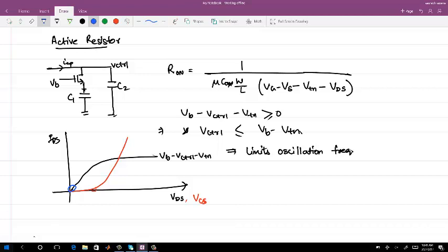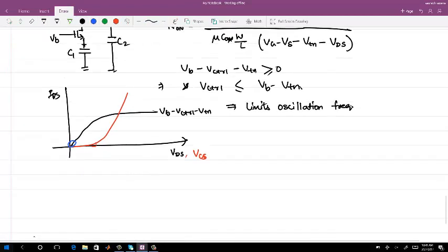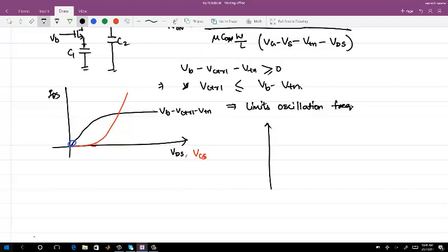Let me say, if I am getting your problem right, even when the VCO has a range going from 0.3 volt to 1 volt, linear VCO, the thing is, this is supplied by V control, right? If V control is getting limited, that's what I'm saying. I'm not actually giving you any in between translation. That's a different case.